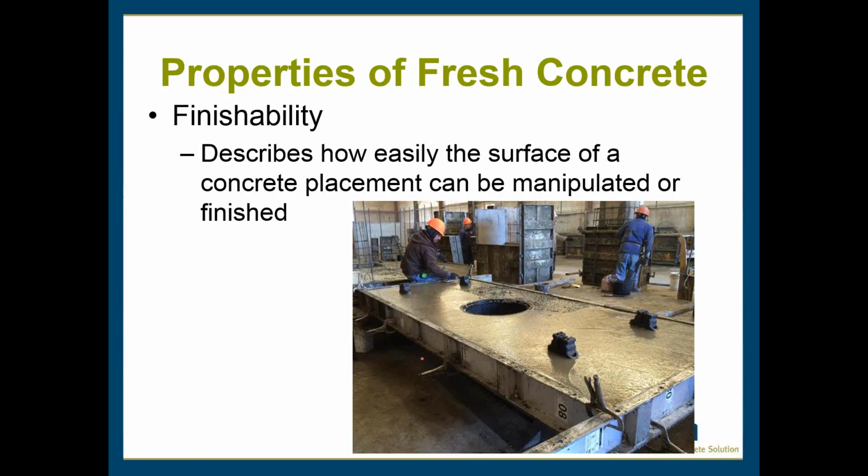If you're using moist curing methods, that is not going to affect the water to cement ratio. That's not getting inside the concrete. It's not affecting the matrix. It's only helping the concrete become stronger, and we'll get into that a little bit later on. And again, if you have any other questions, just feel free to ask them, and Claude or Kathy will point them out to me, and we'll stop and answer them.